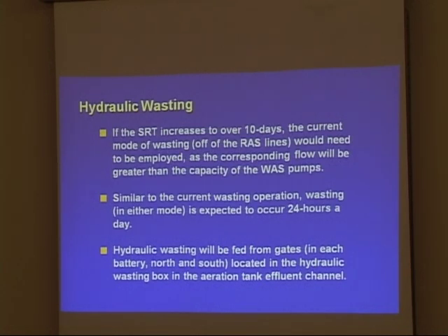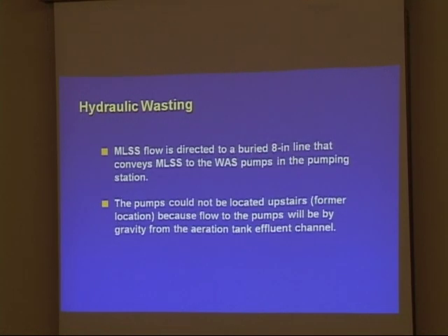Similar to your wasting operation, your hydraulic wasting is expected to occur 24 hours a day. It is fed from gates on the north and south located in the hydraulic wasting box on each of those batteries, so you set up the gates. You also have the ability to open a gate and let scum get diverted and mixed in there as well, to get rid of scum that comes off the top of the aeration tank, so that's something you can routinely do as well.